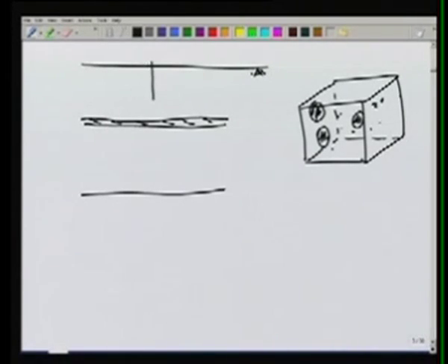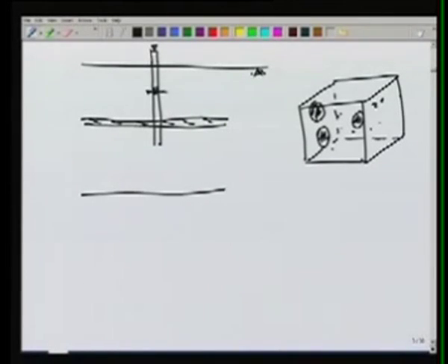If we put a tube here, a piezometer here, water will rise up to a certain level, which may be below the ground level, it may even be above the ground level, in which case it is called a flowing aquifer. Now suppose the piezometric head is here.